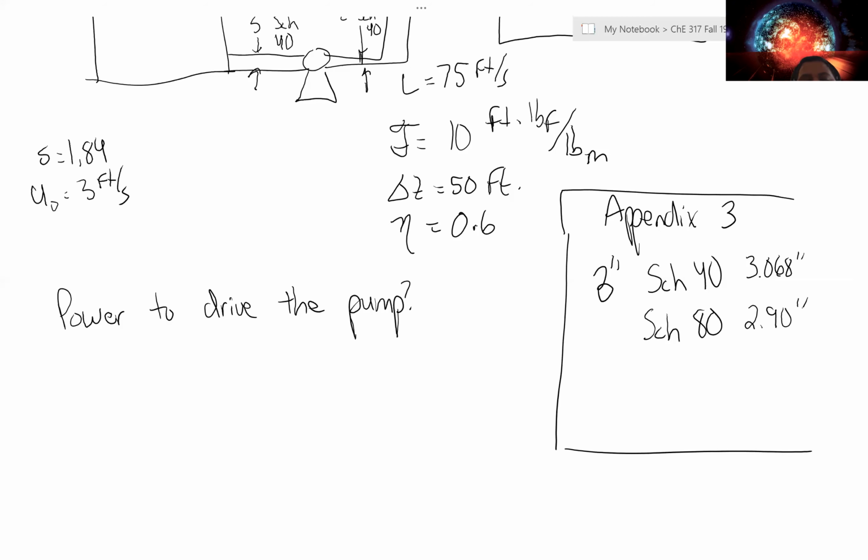Now it's a bit of a pain, but the good news is in this system, as it's defined, the cross-sectional areas for flow are already defined within the table, such that if I'm looking at a 3-inch Schedule 40 pipe, the inside cross-sectional area is provided as